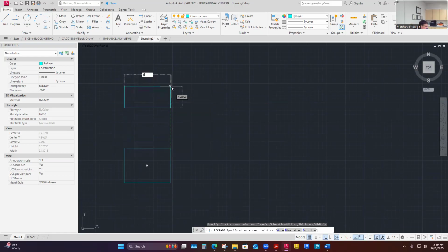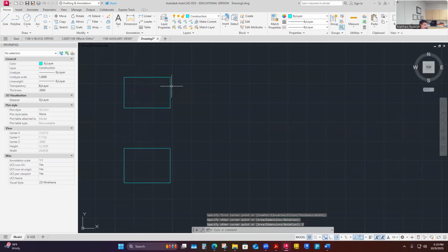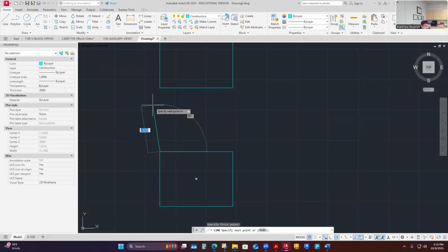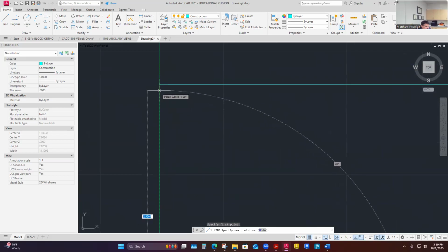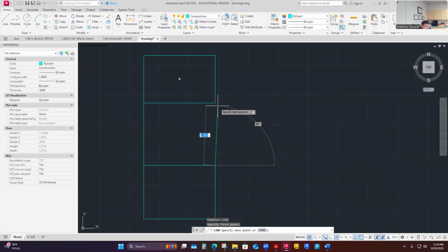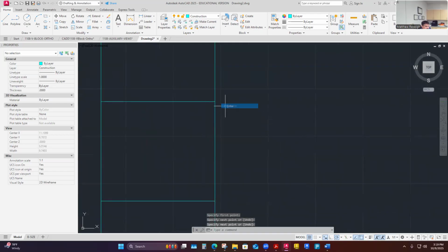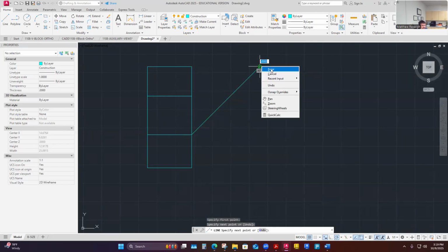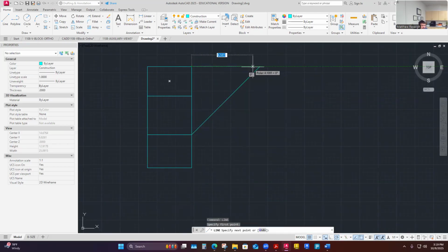So it's definitely going to be 3 by 2 inches deep here. I just want to make sure that I've got those in orthographic alignment, and they look to be lined up correct. Yeah, like that. I'll make my miter line. Make sure I'm going to draw this at 45, not what I have selected right there. 45 for my miter line. If it'll snap, there's 45. There's my top right there. That should be good. And then I'll just project the right side view.